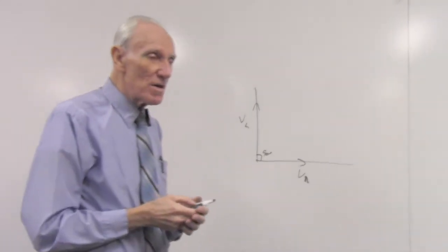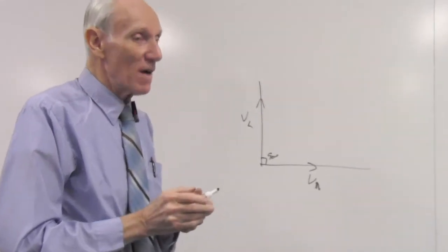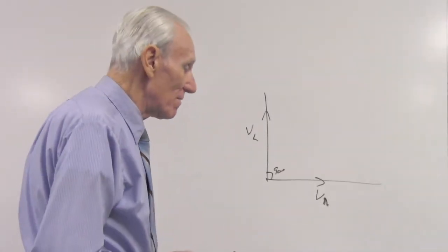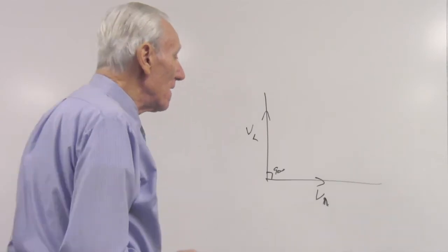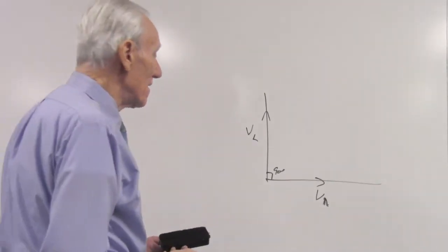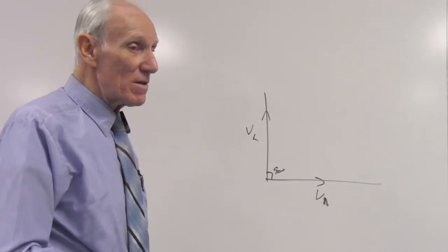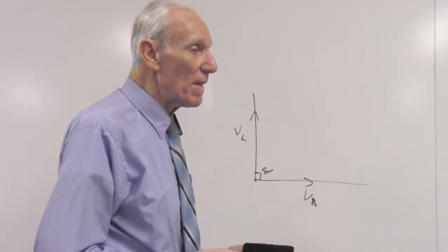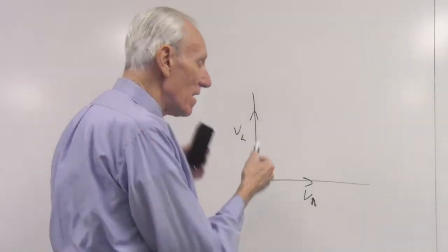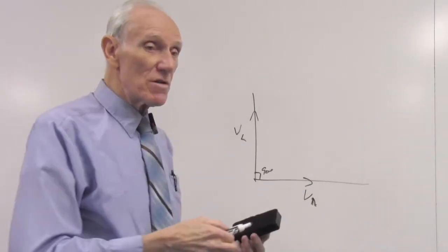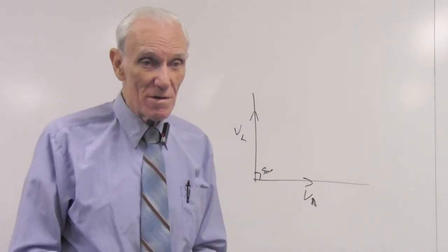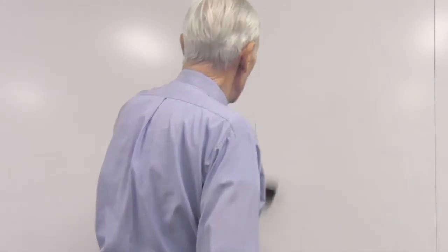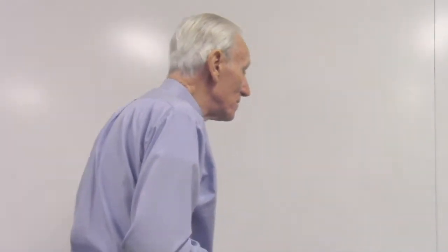But unless you have a superconducting inductor, which has no resistance, any real normal conductor is made up of a coil of wire which has lots of resistance. In fact, in the inductors we have, the resistance of the inductor is as big as the resistance of the resistor. They're both around 100 ohms, depending on which inductor and which resistor you have.